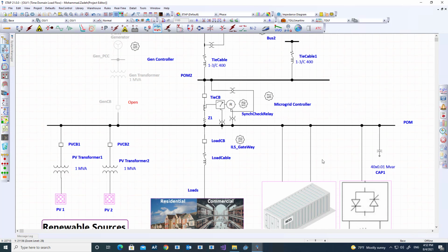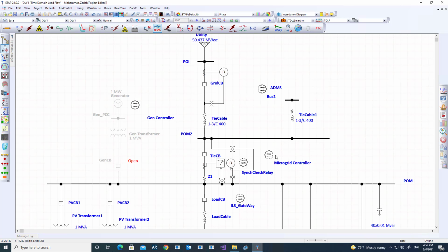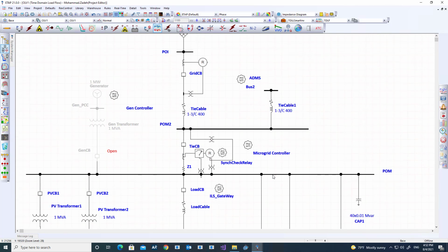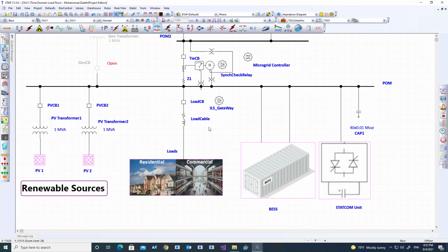So what's going to happen is that if you run this, there is a generation, there is a load, and at certain points in time there's an excess of power from generation over load, so we are exporting to the grid. The job of the microgrid controller is to command a battery to charge at those times. Also at certain points you are importing lots of power from the grid, so it does peak shaving. So I'll just try to demonstrate that simple case for now.